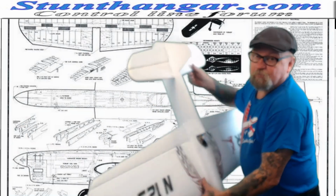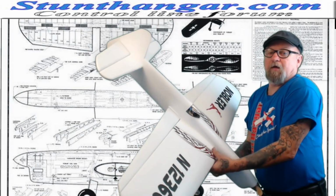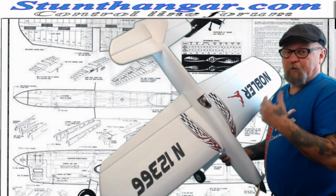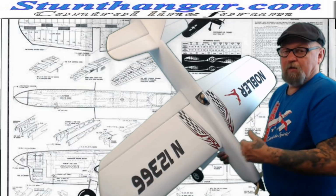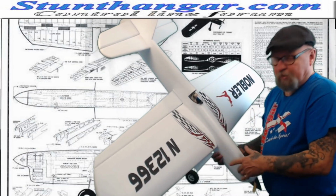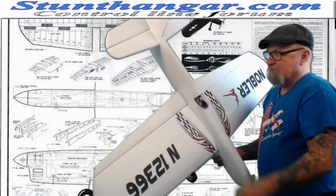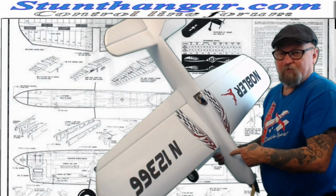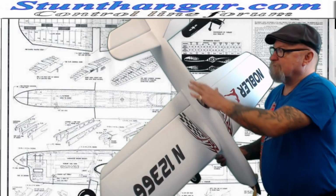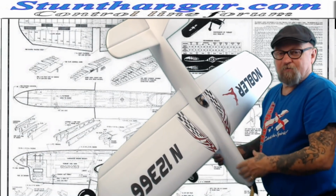This is the physical specimen here of the Nobler. And you ask, what makes this airplane work so well? Well, it's in the numbers. The nose only has to be long enough to balance the tail. So if you build real light, you can have a short nose. And the more the airplane weighs, the more tail heavy it is. So you have to lengthen the nose.